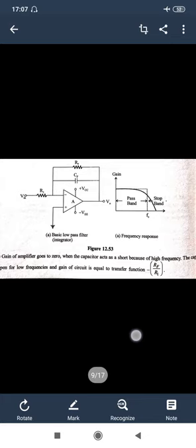But in case of low frequency, it acts like an open circuit. So in this case it is an integrating circuit and an inverting amplifier circuit. We take the output in terms of the transfer function, that is denoted by minus RF by R1. So this is the response and circuit diagram of the basic low pass filter circuit, which works as an integrator. Next is the high pass filter circuit.